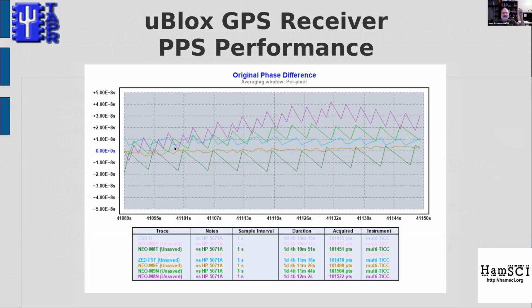You'll also see that some of these are very much a straight line. The GPS itself has some temperature compensation to keep it more accurate, where others, like this purple line, you can sense there's a frequency cycling trend, a bit of a sine wave going on here. I don't know quite what it's from, but that's because of the lower quality oscillator in the GPS unit.